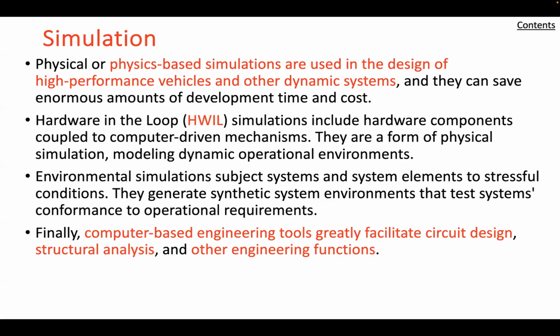And finally, we have wind tunnel testing and the development of air vehicles. An indispensable tool is the aerodynamic wind tunnel. Even though modern computer programs can model the forces of fluid flow on flying bodies, the complexity of the behavior, especially near the velocity of sound and interactions between different body surfaces, often requires extensive testing in facilities that produce controlled airflow conditions impinging on models of aerodynamic bodies or components. In such facilities, the aerodynamic model is mounted on a fixture that measures force along all components and is computer controlled to vary the model angle of attack, control surface deflection, and other parameters, and to record all data for subsequent analysis. As noted in this discussion of scale models, analogous simulations are used in the development of the hulls and steering controls of surface vehicles and submersibles using water tunnels and tow tanks.